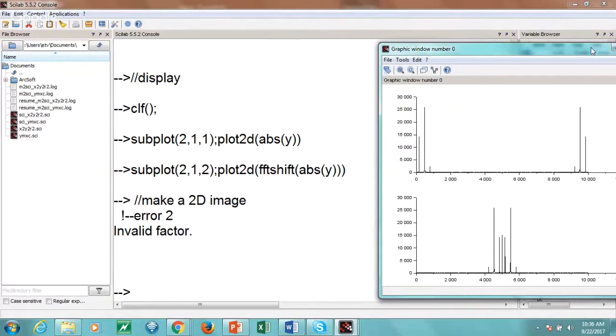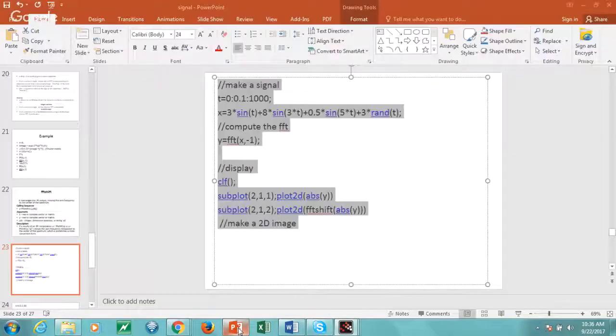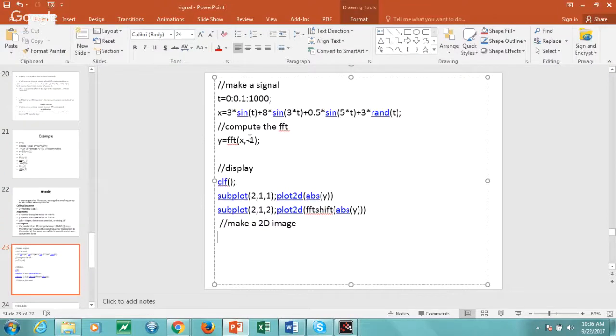If you calculate the FFT and then you plot, you will get this type of graph. And after that you are shifting to the center. When we have given the fftshift command, we are getting the FFT shifted to the center point. So this only we have done here, how to shift the FFT, and after that how to shift the IDFT, or IFFT, whatever you want to call it.